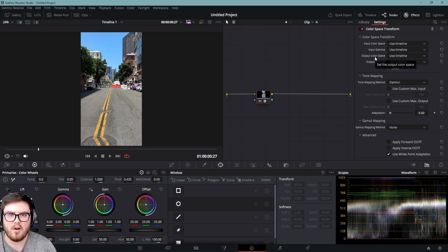This is very important in our visual effects pipeline because we do want to be working with EXR sequences. EXR sequences are like PNG sequences, but they are in a linear color format. And so that means that we're going to have a lot more data and a lot more information. However, if we leave it in an sRGB format like this, it'll have a hard time transferring that data between each other. And so we just want to lay out the groundwork so that everything is flat in the same color space to begin with.